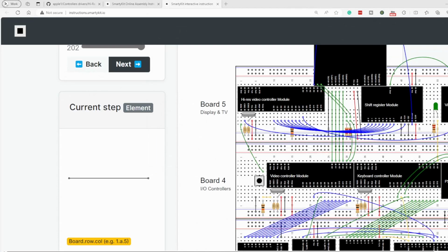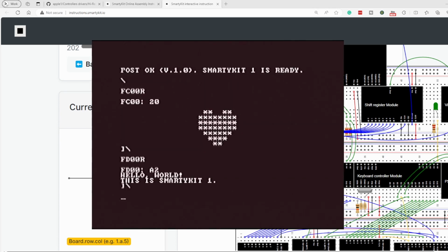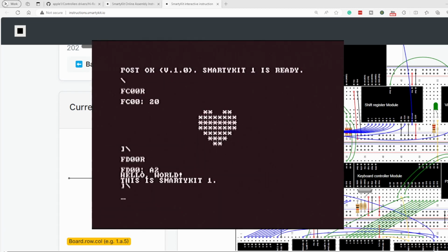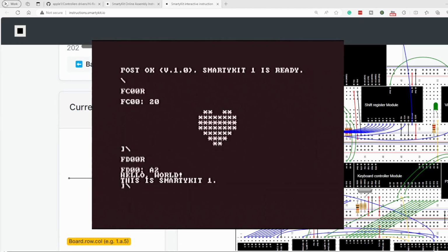So that was an easy change, and I just needed to move the resistor here onto the negative to put it low. Then it all started working, and you get an output display which looks a bit like this. Now, excuse that it is not that clear on this screen. I've got a composite capture module plugged into it, and it's not doing a fantastic job of capturing the composite monitor. But there it is working. It was absolutely wonderful to see that coming up.